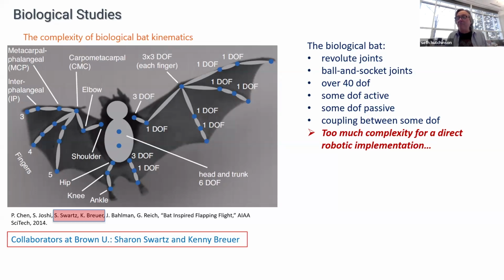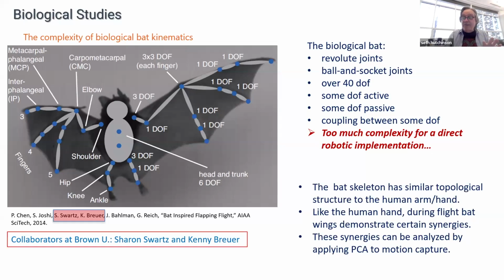It's the reason we don't have airplanes that flap their wings. It's this aerodynamic stuff that has to do with Reynolds numbers. If you want flapping flight to be successful, smaller is better. Hummingbirds flap their wings much faster than falcons, which flap faster than condors, etc. So the bigger the animal, the slower the flapping speed, and the less like flapping flight it is. So we're not going to build a bat robot that duplicates this kind of complexity.